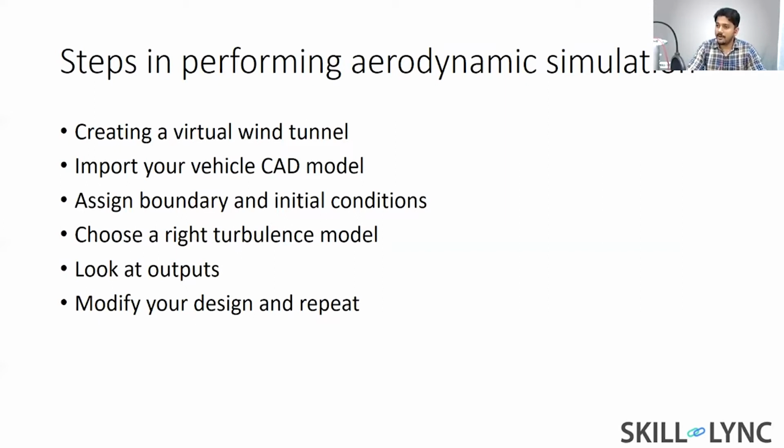And if a particular setup is giving good results, then take that new design and test it out in different conditions. The other thing that students do is they always keep the yaw angle 0, right? And today we talked about it. You need to test your designs at different yaw angles to make sure that your new design is consistently outperforming the baseline design. Only then will your new design become your next baseline design, right?